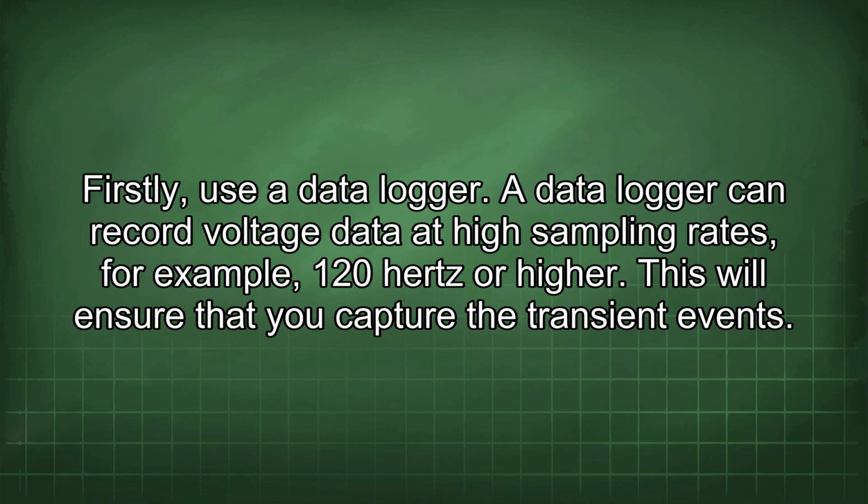Firstly, use a data logger. A data logger can record voltage data at high sampling rates, for example, 120 Hz or higher. This will ensure that you capture the transient events.